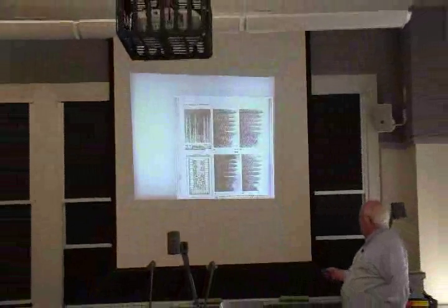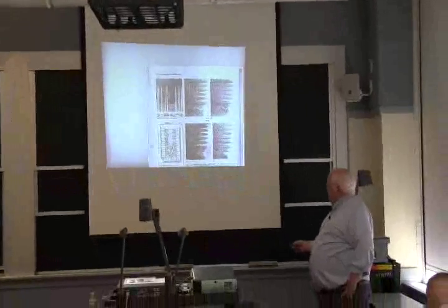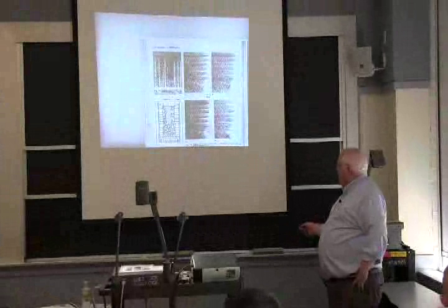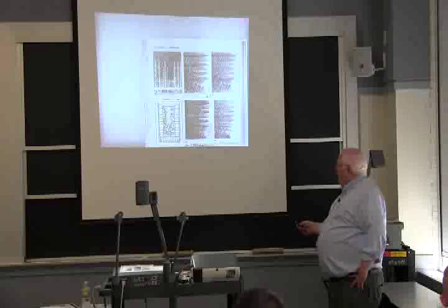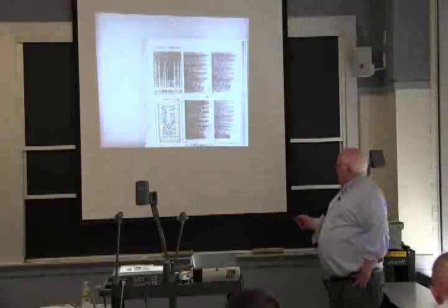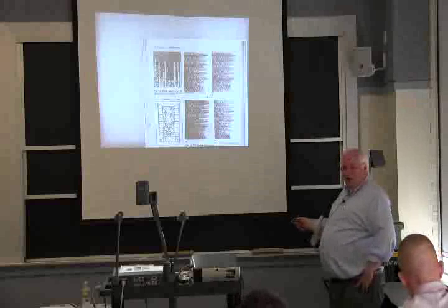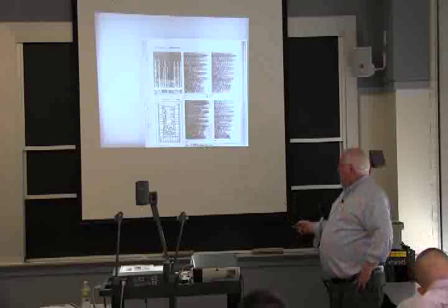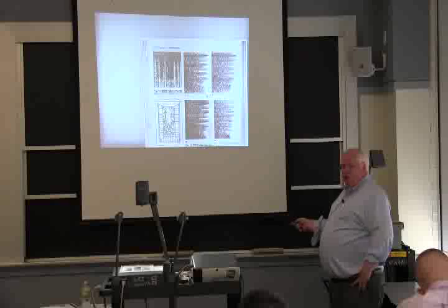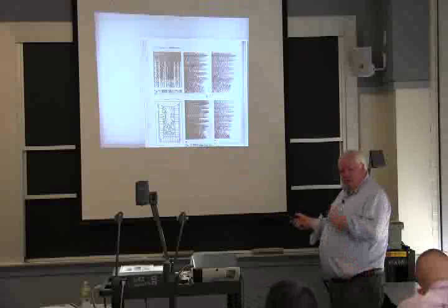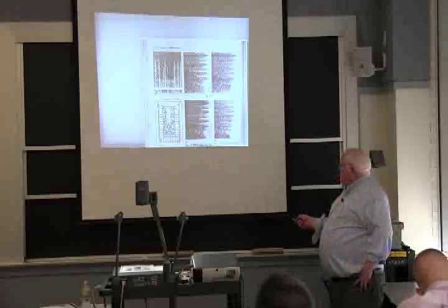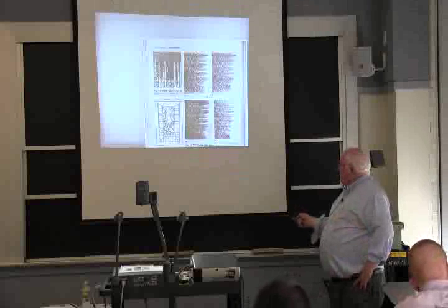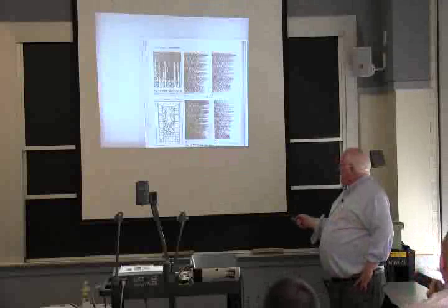When you have an ingot casting, you actually will get the same initial nuclei forming on the outside. When you first pour it in the mold, that's fine grain. Then you'll get columnar grains, and then you may have dendrites form in the center. And through all this, you get fluid flow in the liquid as it's cooling down. Remember, in a big casting, this could take hours or days to cool down, and the liquid is getting enriched in one of those other elements. So the first stuff that solidifies is very rich. In an ingot cast steel, a rimmed steel, this would be a very pure iron alloy on the surface.